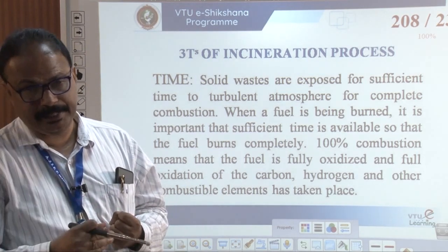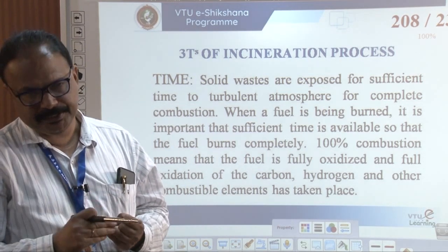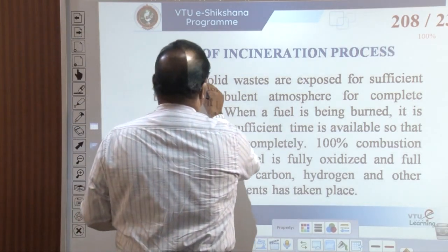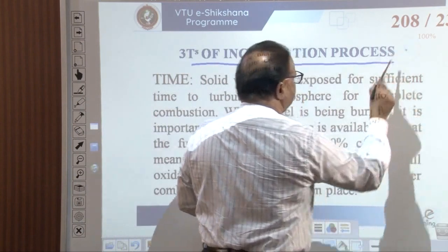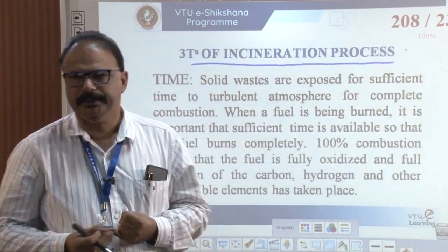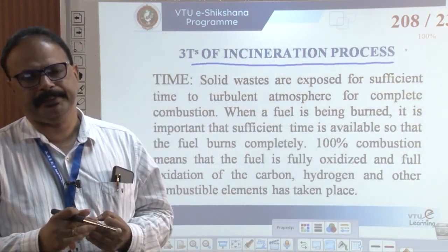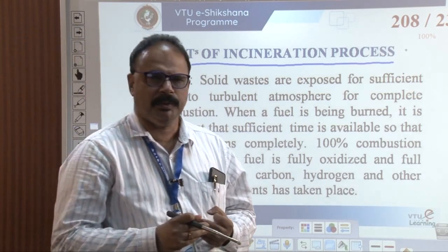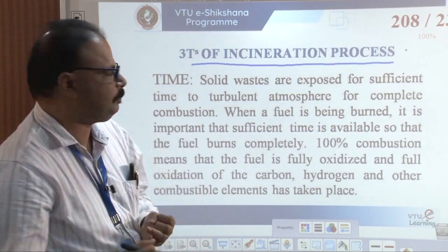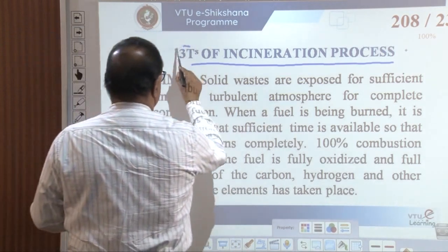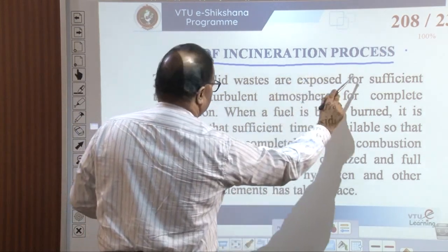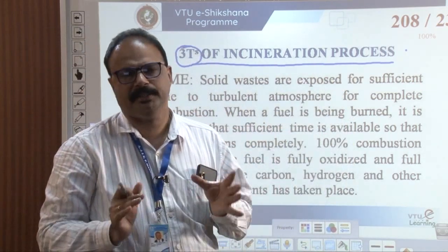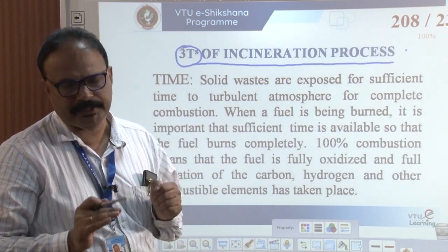There are 3Ts: time, temperature and turbulence. The 3T process of incineration, okay. Time, temperature and turbulence are called the 3Ts. In incineration, there is burning of the waste.